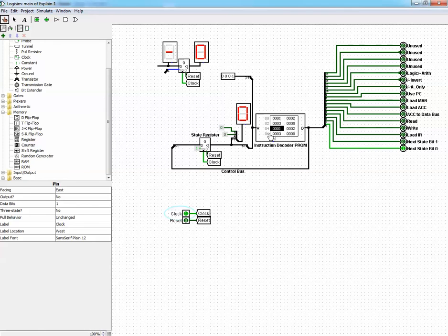So we went to this state. So why did we pass by this state? Because it's a Mealy machine. This is why you need to tick the clock first and then see which state it went through. Okay, let's tick the clock again, it goes to that state. Tick the clock again, goes to that state, and goes to that state again.